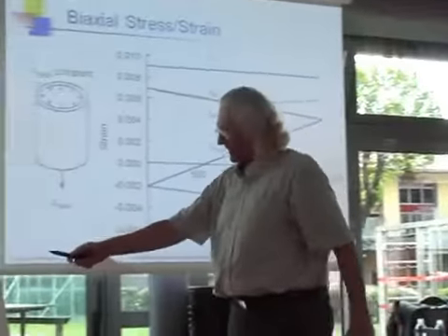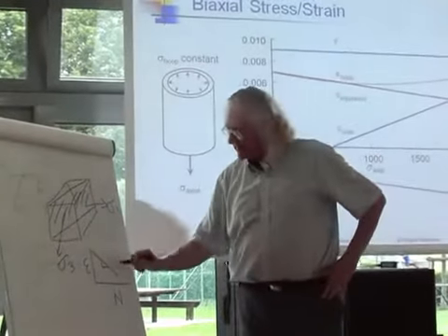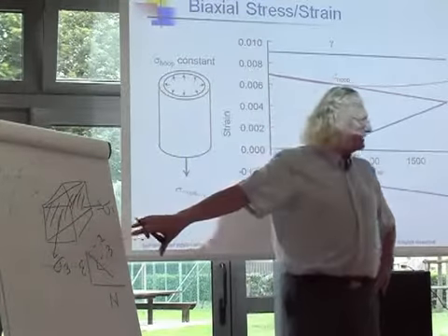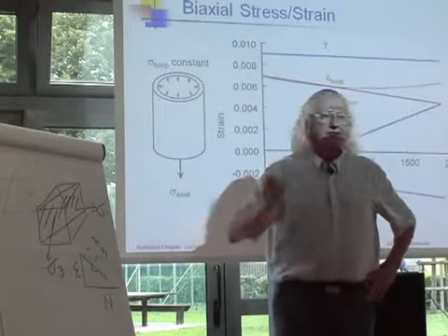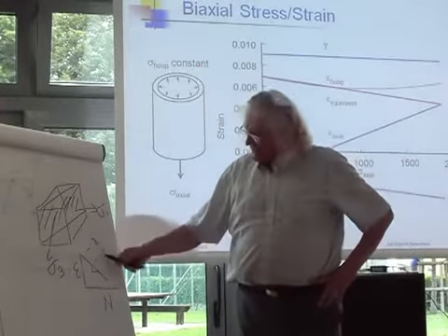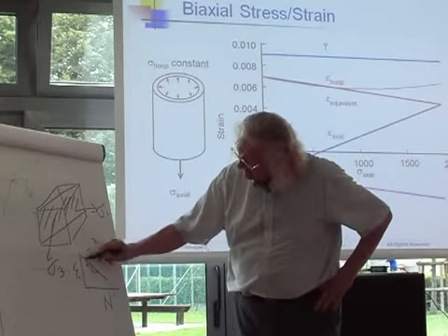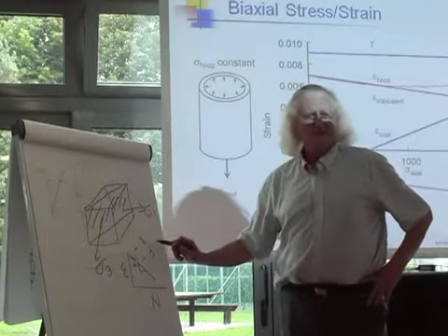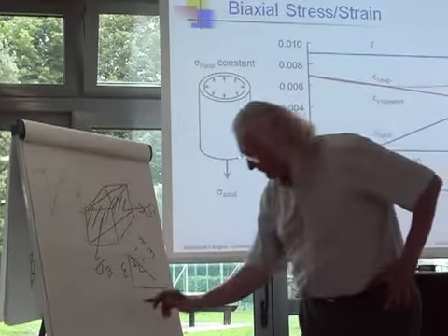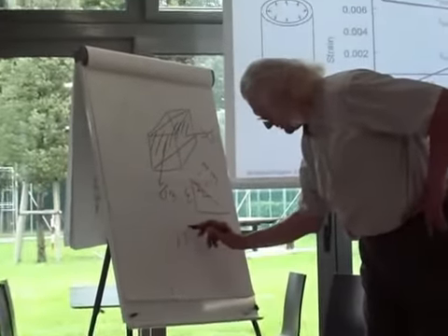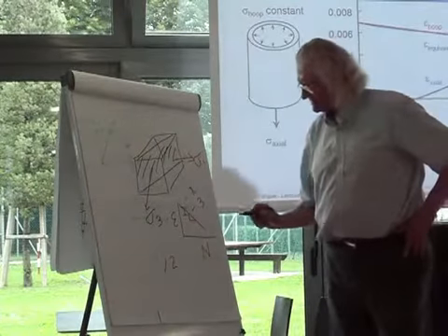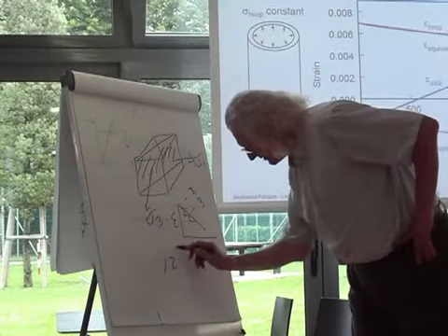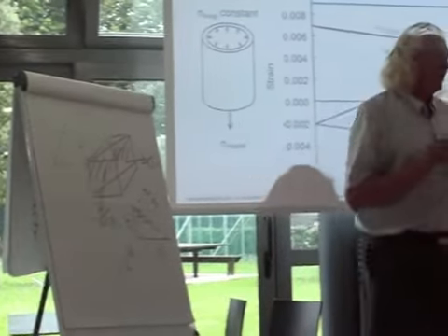Okay, so if you look at fatigue data, maybe this slope is minus 0.2 or maybe minus 0.3 or something like that. That means that if I change this by 20%, it's 20% raised to this power. So 1.2, and well, let's use this one. Minus 0.2 turns out to be what, fifth power dependence? So what is 1.2 to the fifth power?